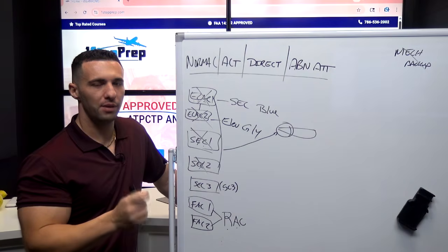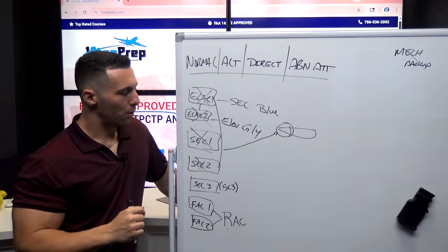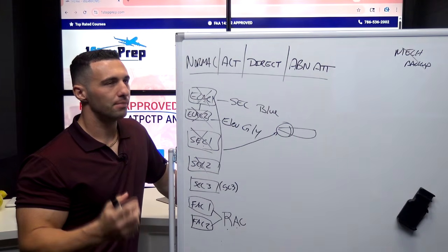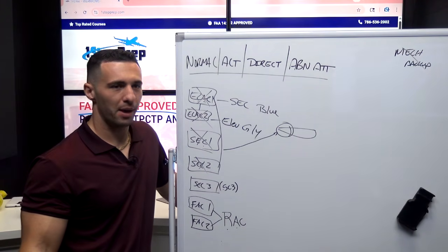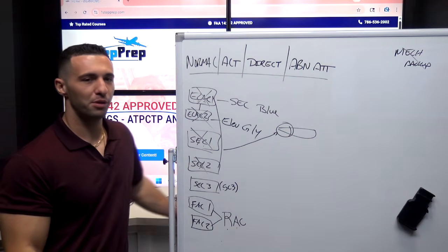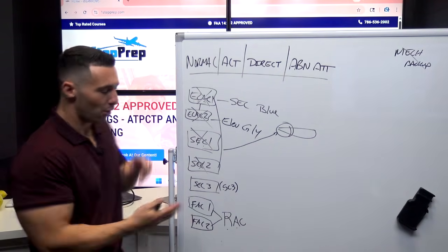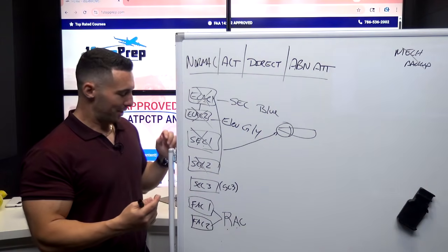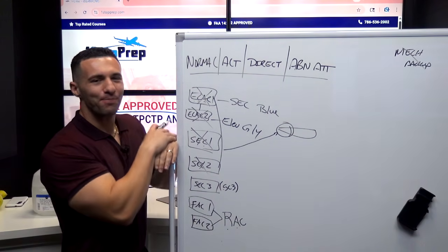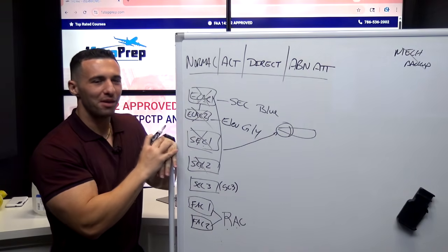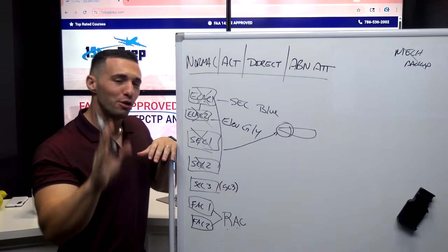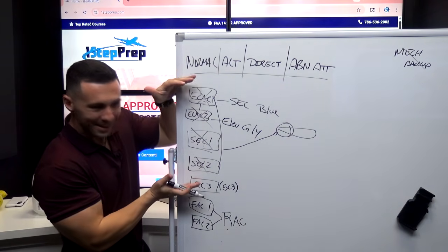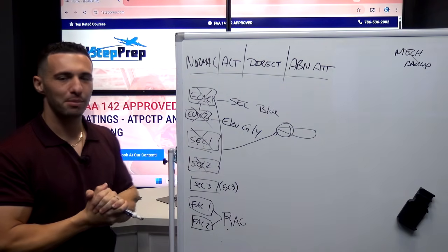You lose control of the elevator. Now, usually when we talk about mechanical backup, and I say, hey, how do I get to mechanical backup? Everybody says, well, I lose all my flight control computers, which is not incorrect, because obviously if I lost all 7, that would include the 4. So not necessarily incorrect, but a more correct, more specific, more detailed response, in my opinion, would be to say, if I lose pitch control to the elevator via these 4 computers, that is going to place me in mechanical backup.